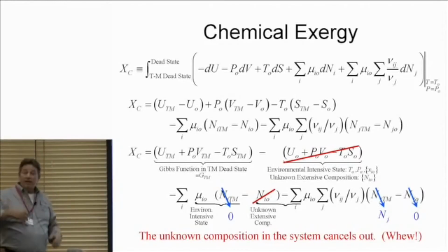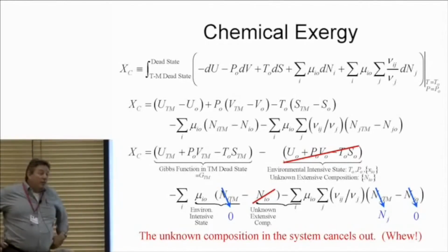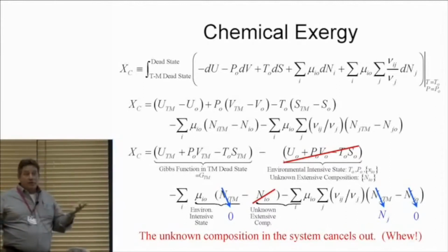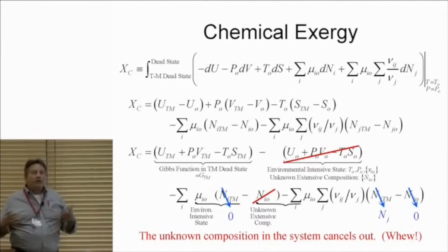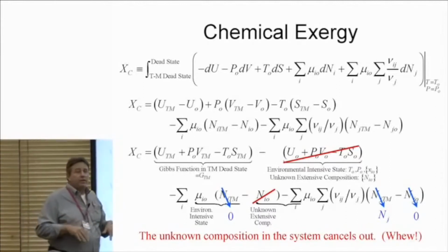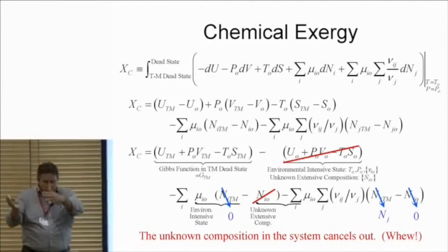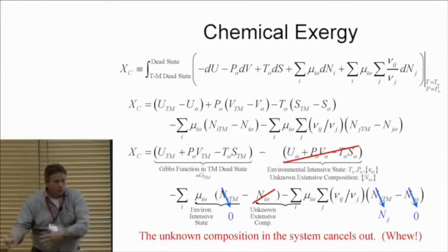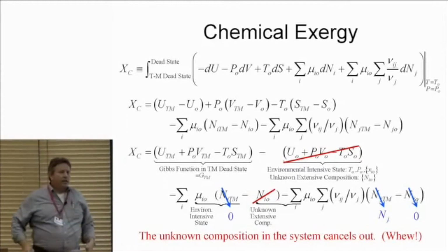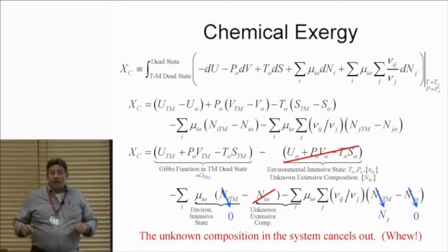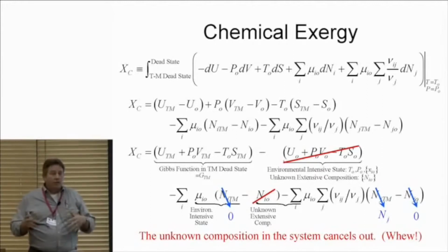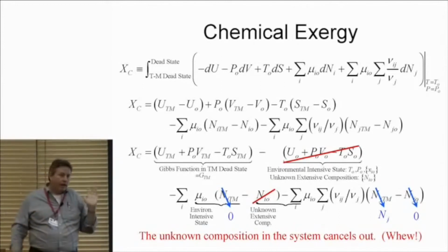Now, if we go back to the beginning, if you've looked at a book like Zargut's book on exergy, anybody? There's a distinctly different way to do this, right? The different way is you construct something that has a bunch of reversible machines that will take the resource until you get it down to the dead state. The tricky part is, it's just great if you can figure out the path of the machines. It's really bad if you get to the point where you can't figure out where the boundary is and you can't put the next machine in to get you through the path.